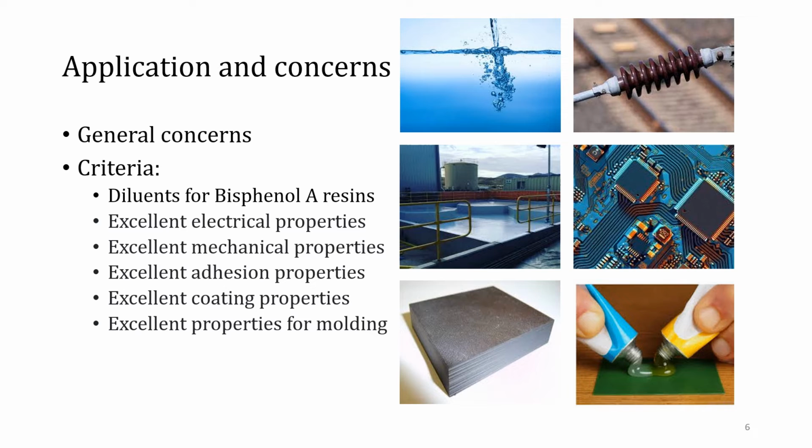By using the reaction of epoxy group and acid, the cycloaliphatic epoxy and the resin containing carboxyl group can be mixed and cross-linked to obtain a coating with excellent performance, which is used in finish coats, automobile primers, and industrial coatings, which need a relatively high film forming property.